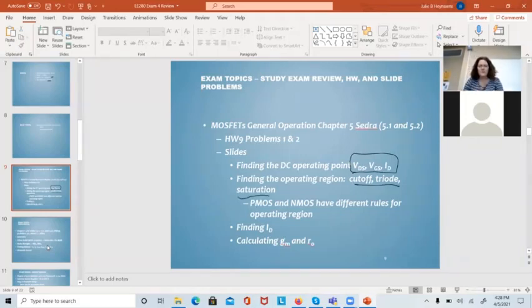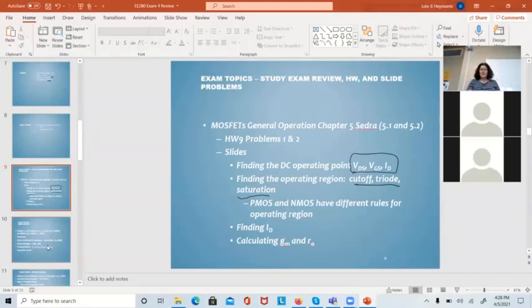Yes. NMOS and PMOS. Given the voltage at the gate, the voltage at the drain, and the voltage at the source, given a picture that looks like this, 1.2, 0.8, 0.2, can you tell me what region of operation it's in, not knowing, having the drain, the gate, and the source labeled?